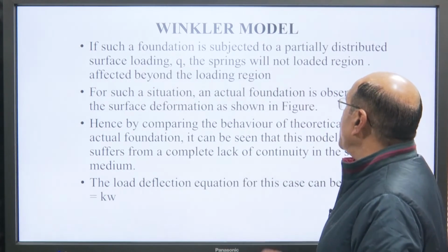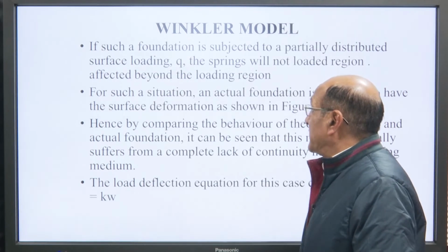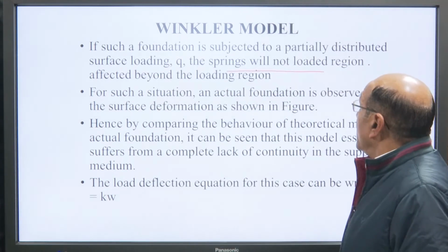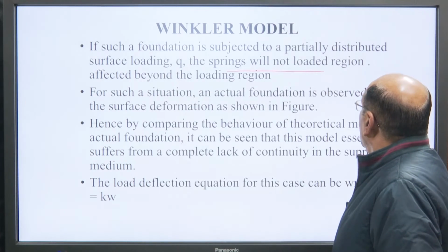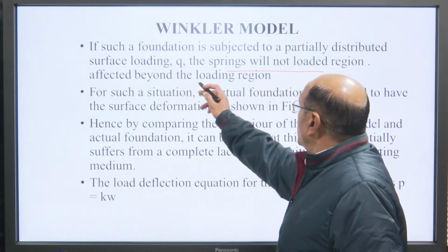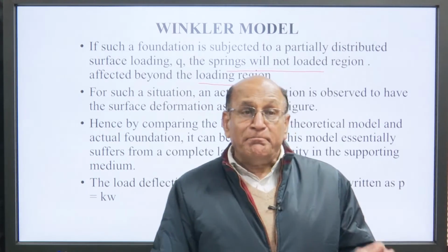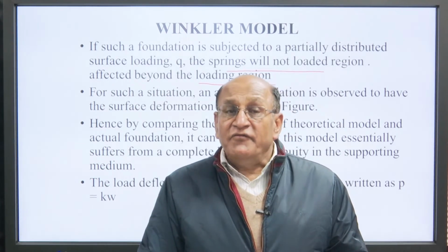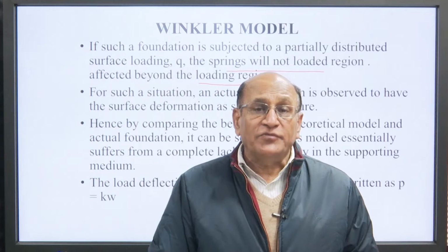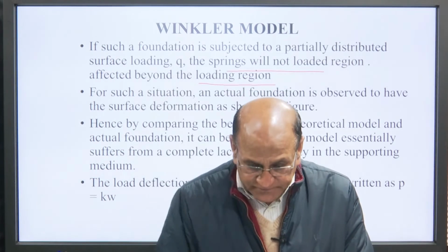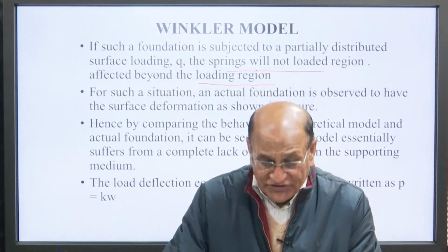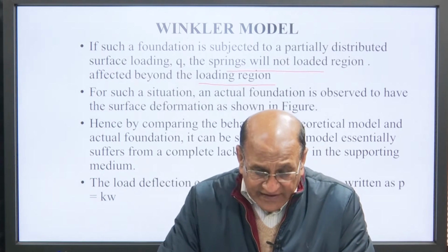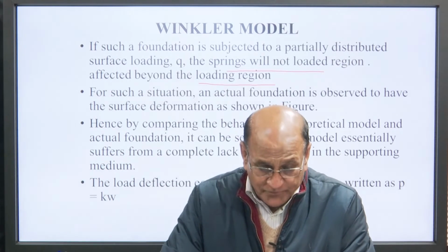If such a foundation is subject to partially distributed surface loading Q, a spring will not be loaded in a region affected beyond the loading region. So, this is the base of this Winkler's model, meaning the load will not affect away from the loading area. For such a situation, an actual foundation is observed to have the surface deformation as shown in this figure.